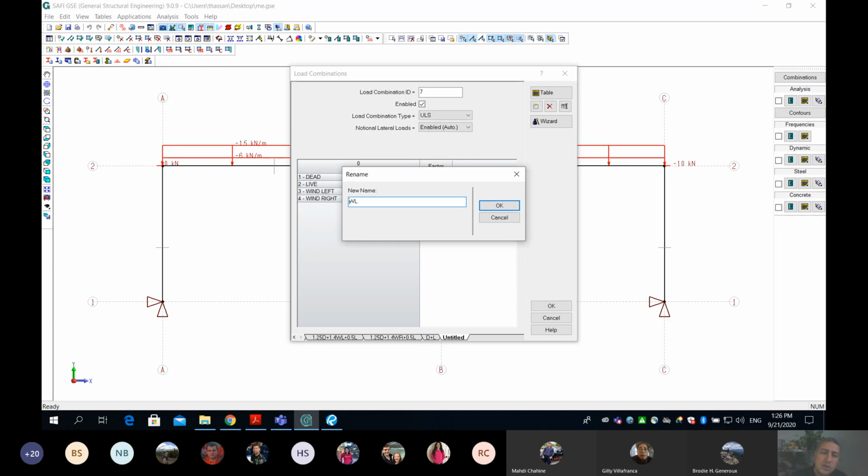Some of you may think we need to find the deflection or the sway of the building under the wind, but you will see in my class, probably not today, but sometime next class, we do not do that. We only find the deflection under 75% of the wind load. Only 75%. I'm going to tell you when the time comes why 75%. Why not one?